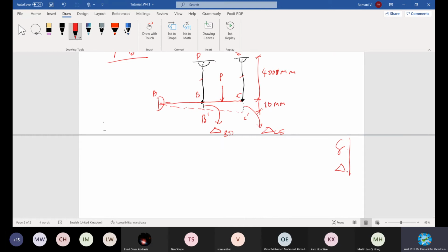So remember these diagrams, everything, and then do one by one. I have done the free body diagram already. The solution starts for the wire or cable CE, let me start with CE. For CE, by definition, how do you calculate the strain? The strain value at CE.